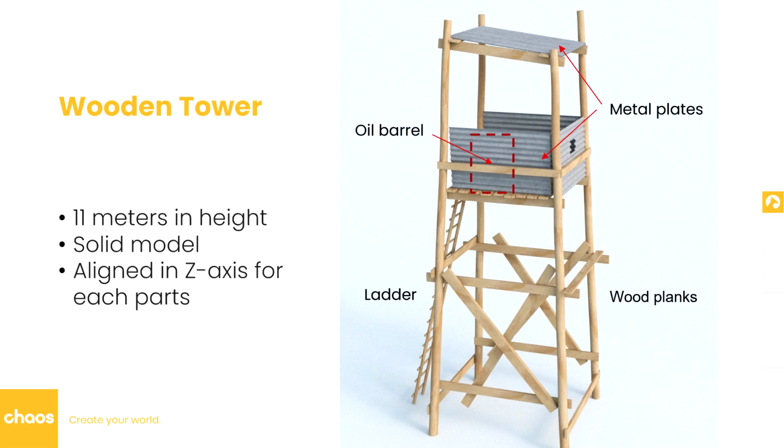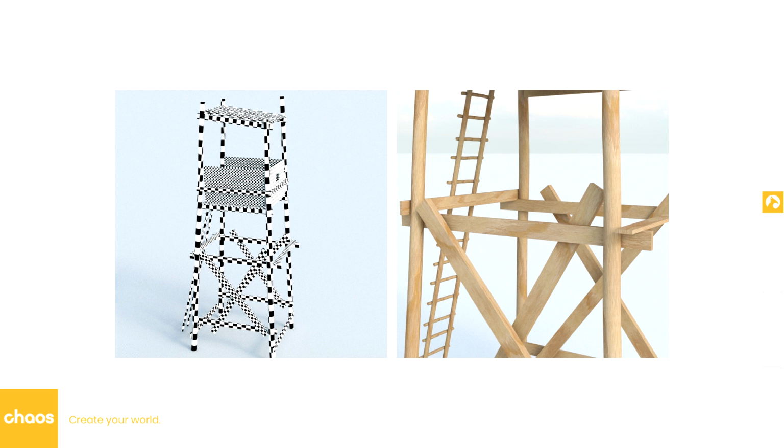When working with fluid simulations, it's crucial to ensure that the model is watertight. This means there should be no open faces or errors when applying an STL check modifier. If there are any issues, Phoenix might encounter difficulties when voxelizing the model during the simulation process. Let's take a closer look at the model.